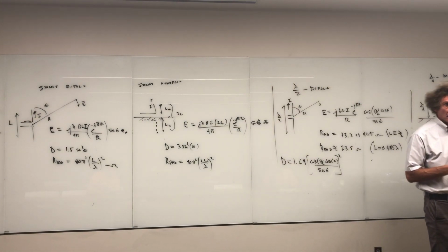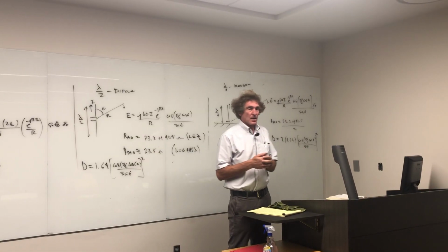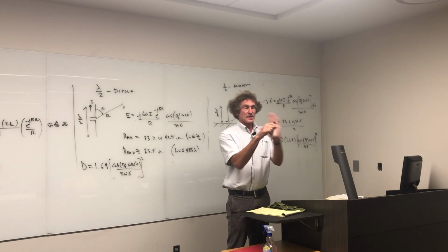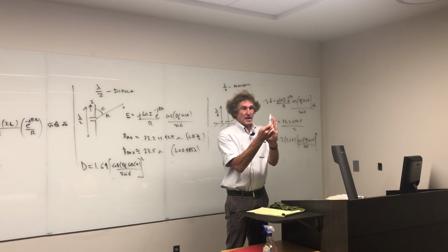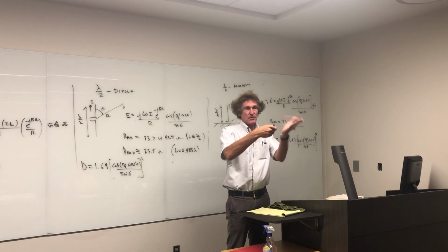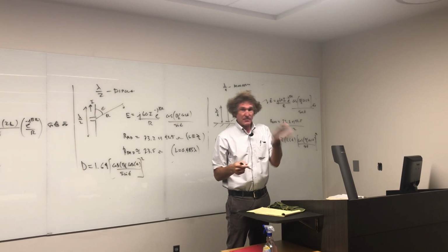Elaborate what you're talking about with it exploding because of the reverse current. I thought it would be due to the internal resistance causing... Well, it does heat up, but the problem is when you have a polarized dielectric, everything's aligned one way. Now when you drive current in there the other way, they try to flip, and that causes frictional heating. You're right, it is thermal heating, but it'll blow up. It's sort of like a microwave kind of.